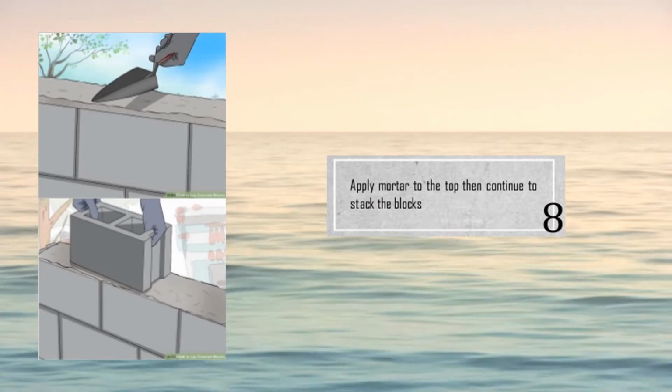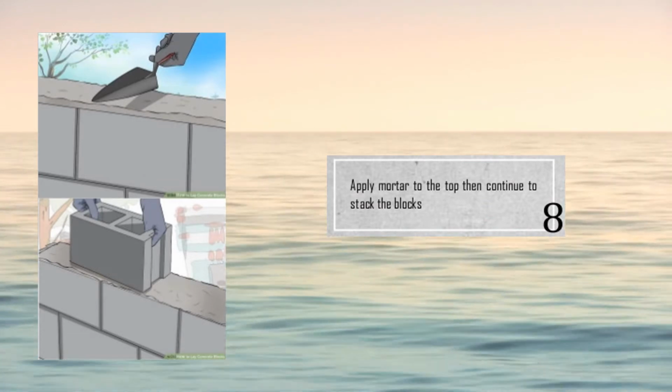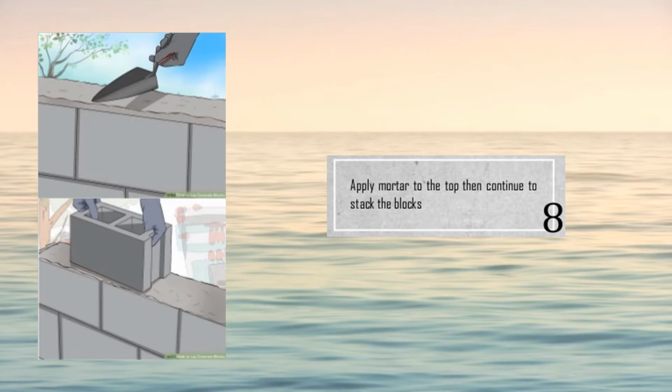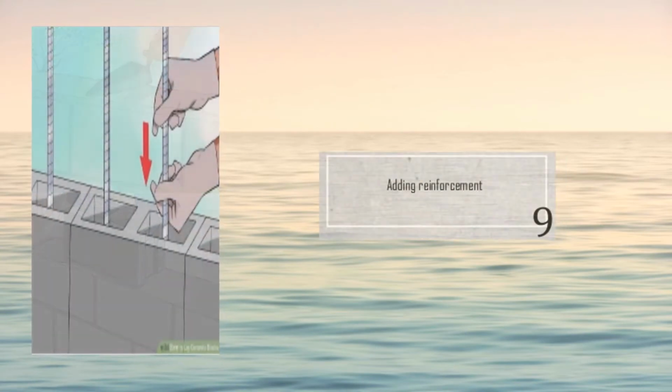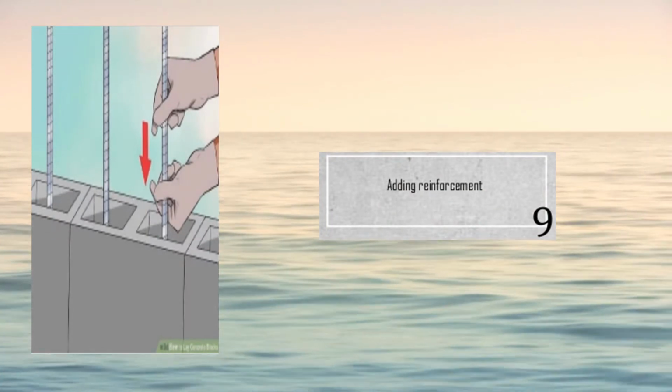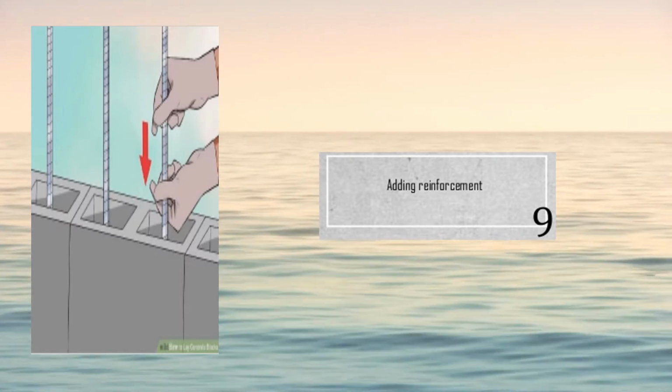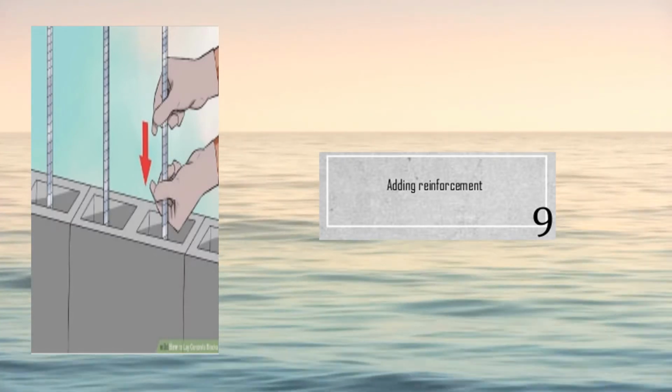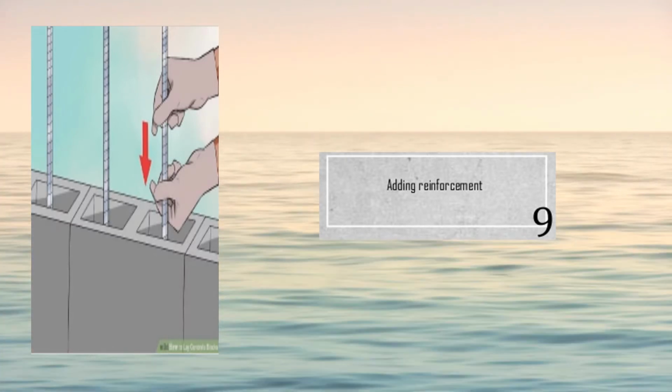Eighth, apply mortar and continue further with laying. Ninth, during laying, add the reinforcement where necessary according to the specification and design to strengthen the wall.